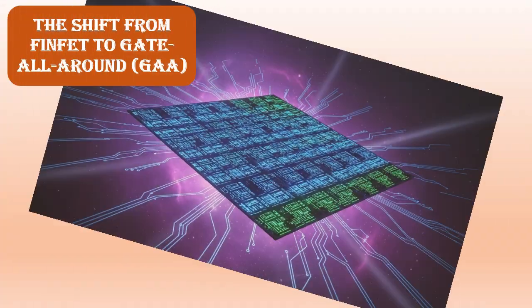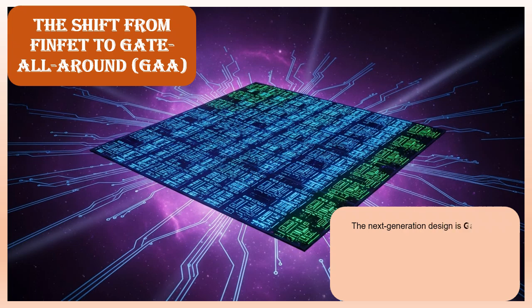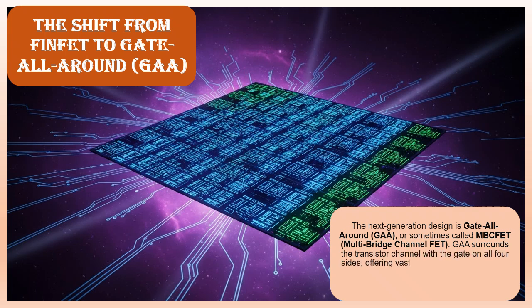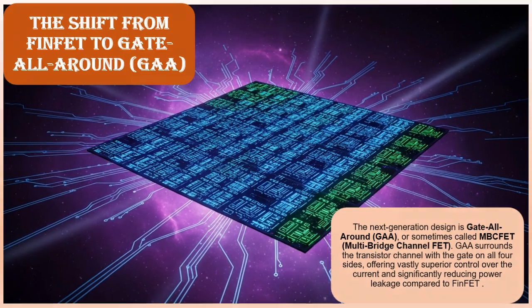The next generation design is Gate-All-Around, GAA, or sometimes called MBCFET, Multi-Bridge Channel FET. GAA surrounds the transistor channel with the gate on all four sides, offering vastly superior control over the current and significantly reducing power leakage compared to FinFET.